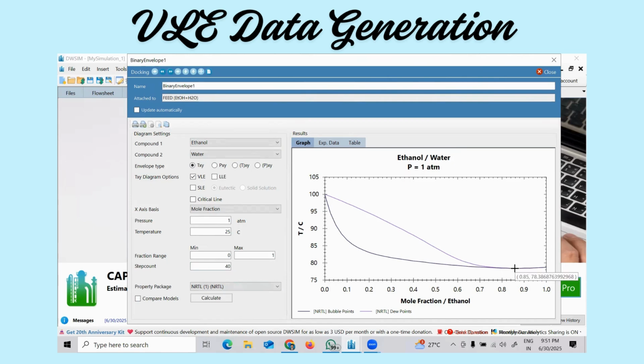See, azeotropic means what? The temperature is constant at one particular temperature, and both mole fractions of the ethanol and water will be equal. So if I move the cursor, you can see how it is changing. See, the bottom one is a bubble point curve and the top one is a dew point curve. If I go on doing this, at one place you see almost they will be same. So it shows an azeotropic system.